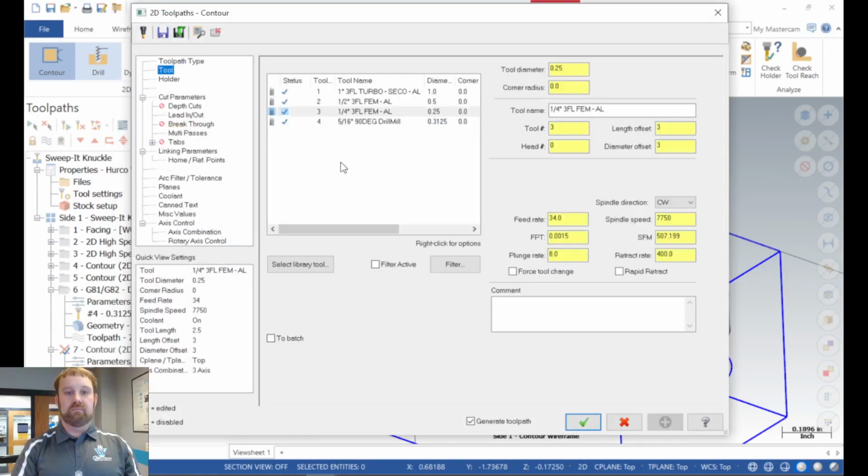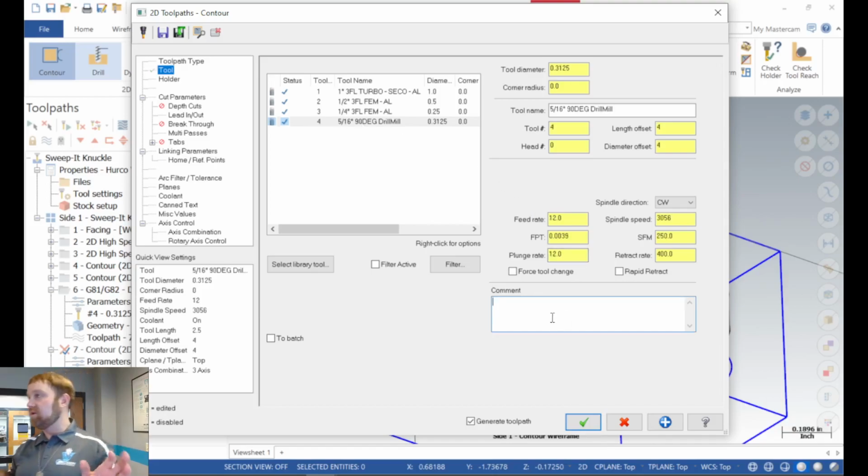Tool, still that drill mill. I'm okay with using the feeds and speeds for the drilling. It's slower than it needs to be for this tool, and we could change it, but for us, it'll be okay. You're going to find out that you're going to have a lot longer in setup and adjustments than what it actually takes cycle time to run this part, or 2 parts, or 3 parts, or 4 parts. The cycle time's not the issue here. We're not trying to split hairs. We're going to tell it that we are going to chamfer. Edge of island, side number 1.